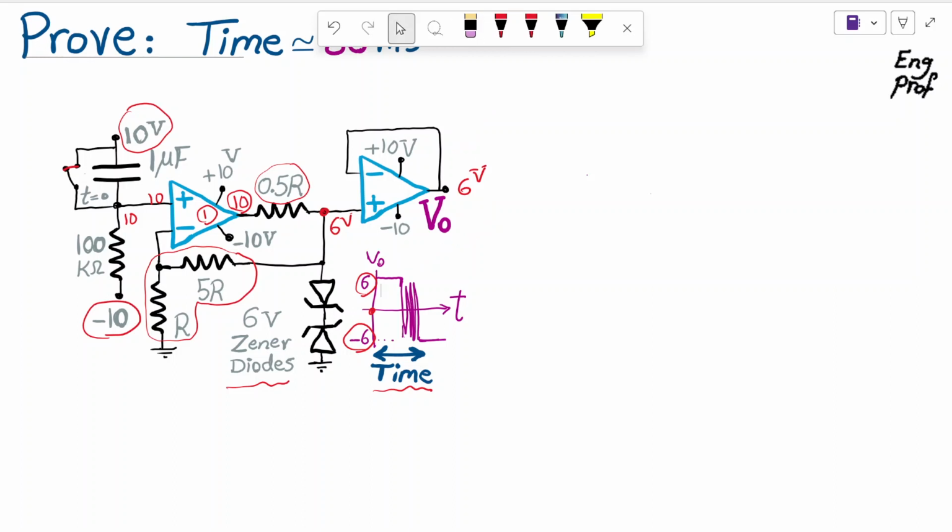At time 0, this switch actually opens. So at time 0, this switch opens, and because of that, the cap voltage, right after 0, is still 0, but there is now a current that is passing through the series of R and C, and it starts charging up the cap. So we know that this situation here is a series RC circuit,